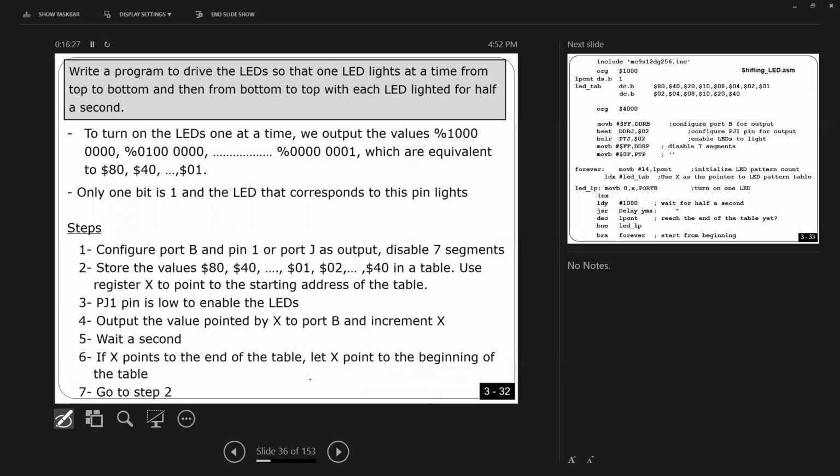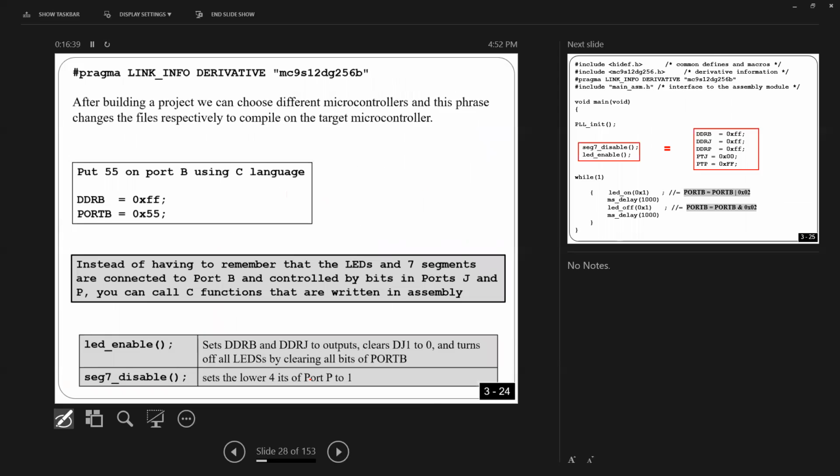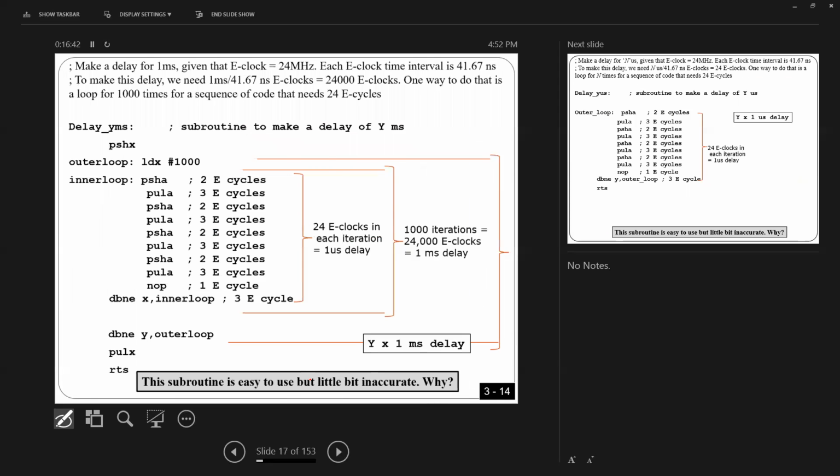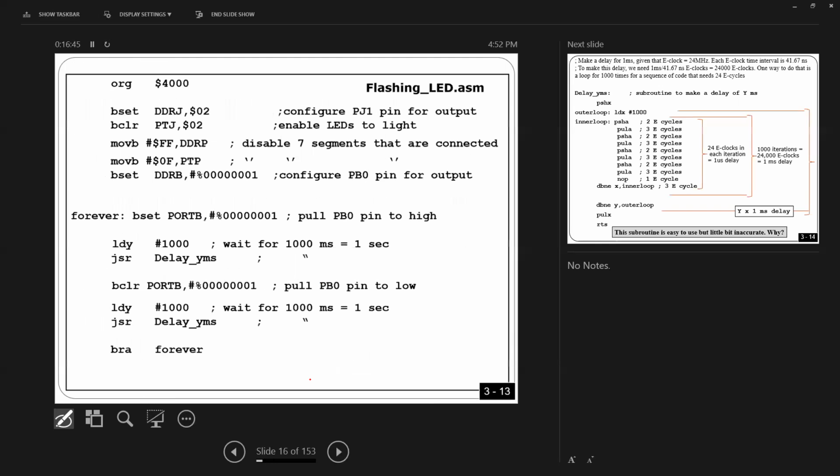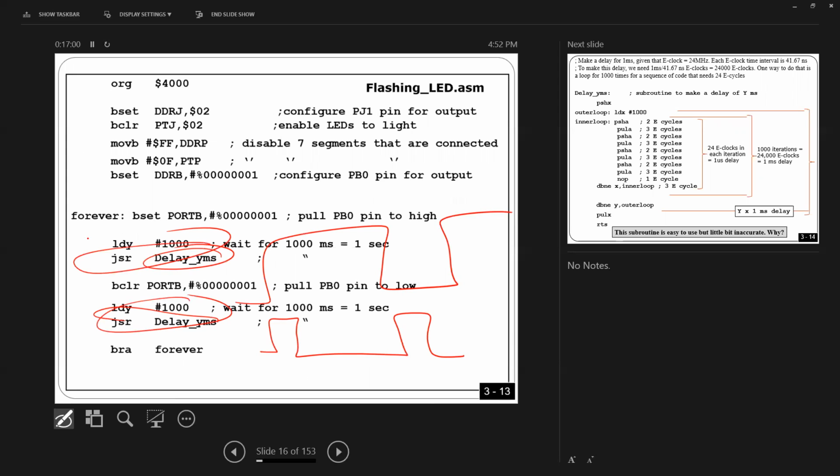Okay. Coming lab. In the coming lab, as I told you in the lecture, I made it easy because this is the first lab where you have to use the board. It's going to be a little modification to this program, but I'm going to ask you to generate different square waves. All you have to do is play with the amount of the delay to generate different square waves. The coming lab needs a scope to connect to the pins to see the signal by yourself, right? So it needs a scope.